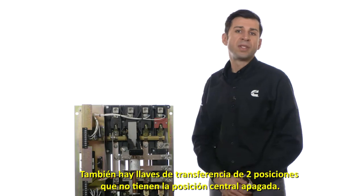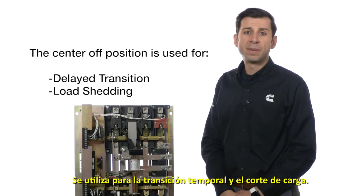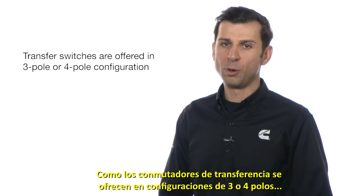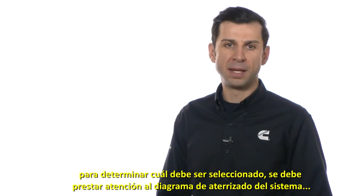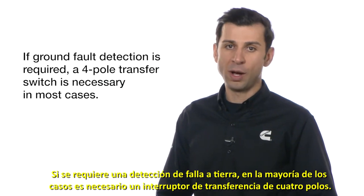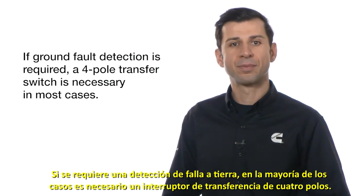There are also 2-position transfer switches that do not have a center off position. The center off position is used for delayed transitions and load shedding. Since transfer switches are offered in a 3-pole or 4-pole configuration, to determine which one to select, attention must be paid to the system grounding scheme and ground fault protection requirements. If ground fault detection is required, a 4-pole transfer switch is necessary in most cases.